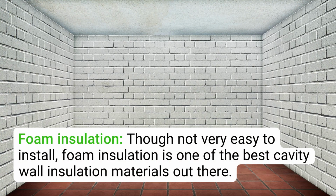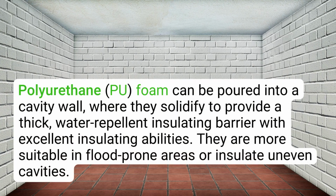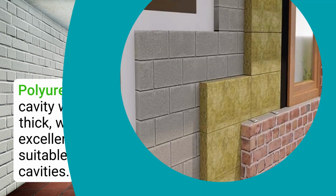Foam insulation. Though not very easy to install, foam insulation is one of the best cavity wall insulation materials out there. Polyurethane foam can be poured into a cavity wall, where it solidifies to provide a thick, water-repellent insulating barrier with excellent insulating abilities. It is more suitable in flood-prone areas or to insulate uneven cavities.